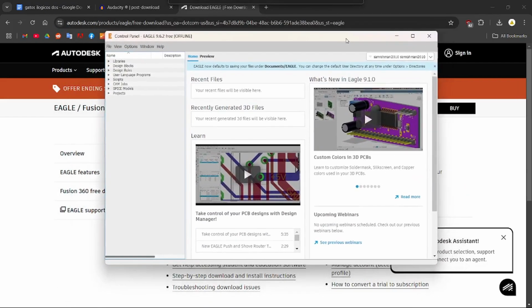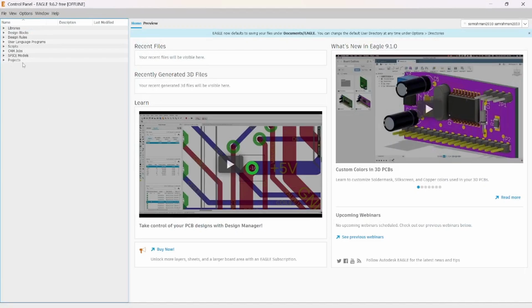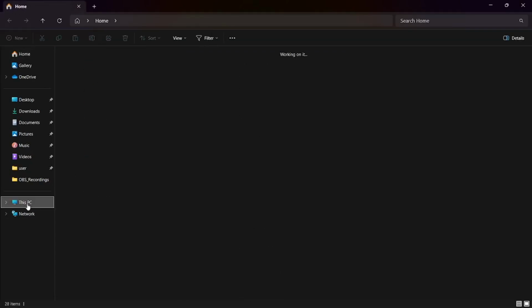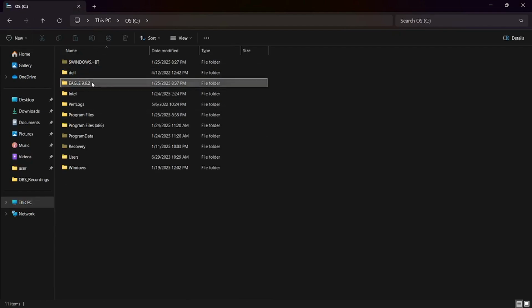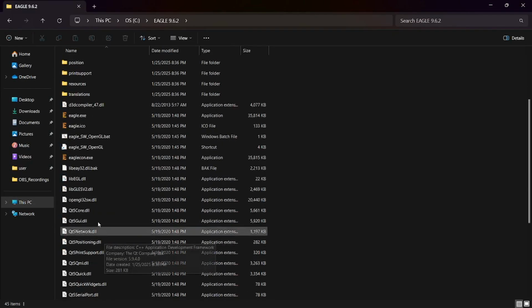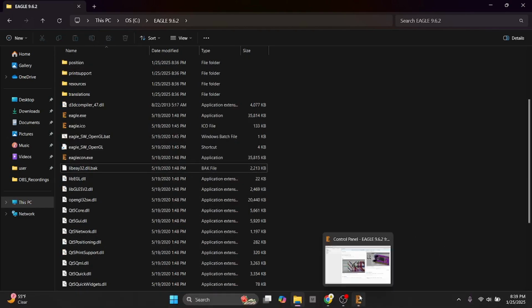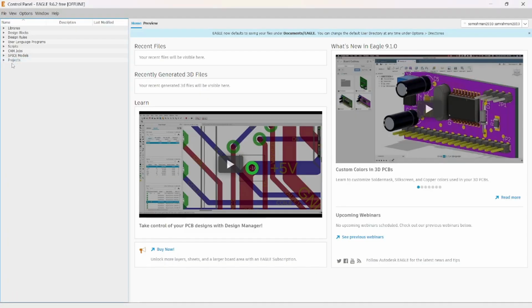This is a program I used to design the files. There is one quirk on it though that I've had every time I've installed it. You have to go under the Eagle files. Normally, this doesn't have the .back extension. You have to add that yourself. But once you do, Eagle boots up fine.